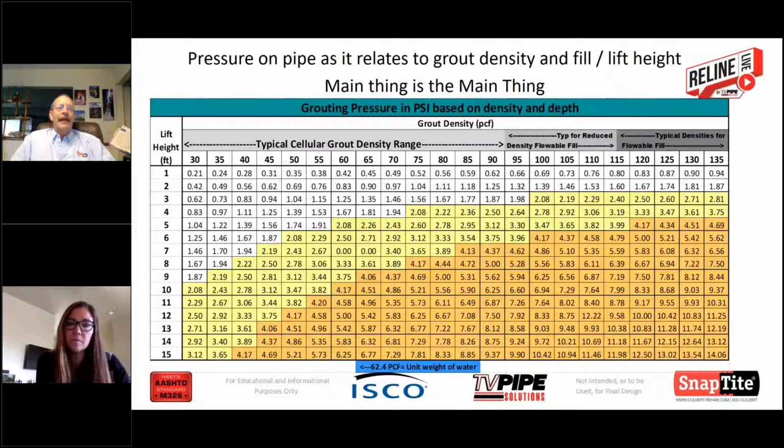Polyethylene is a very elastic material, and it has a high degree of allowable strain. In the seismic committee that I'm working on with ASCE, we're looking at 5% allowable strains or bending due to earth movements. And there's strong evidence done by EPRI and others that shows that 10% allowable strains may even be acceptable for the polyethylene material.